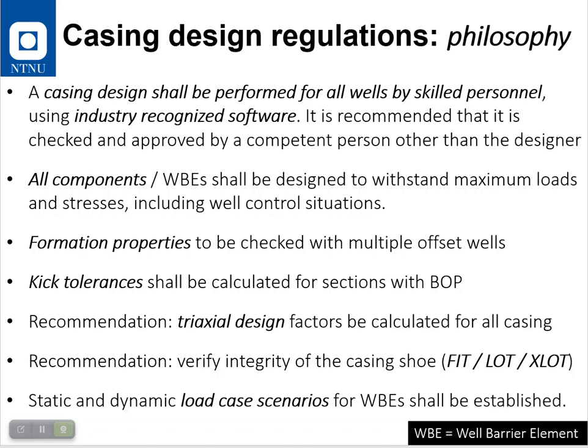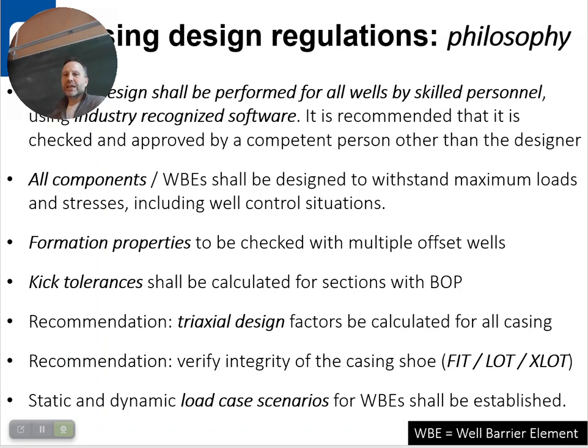Yeah, and there we go over to what is again a recommendation, and that's to do integrity checks with the FIT, leak-off tests or extended leak-off tests. Now, just as a quick thing for you guys, what happens if your leak-off test or FIT shows that the shoe is weaker?